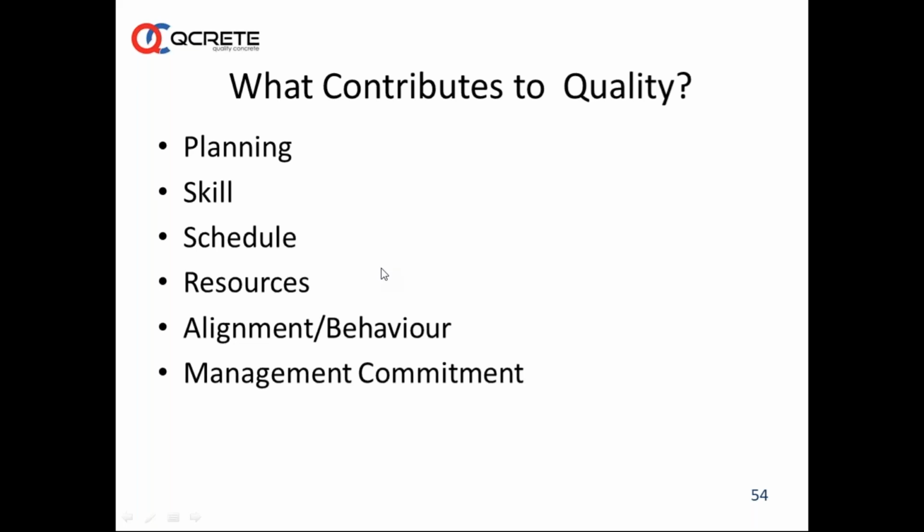So what is the meaning of one sample? One sample means 3 cubes for 28 days, and these 3 cubes' average will give one result. So 7 days also we take. Generally we take 3 cubes for 7 days and 3 cubes for 28 days. Here there are some customers who will say you take one cube from every truck, or one truck 2 cubes, another cube in another truck. All these things some people will say actually.